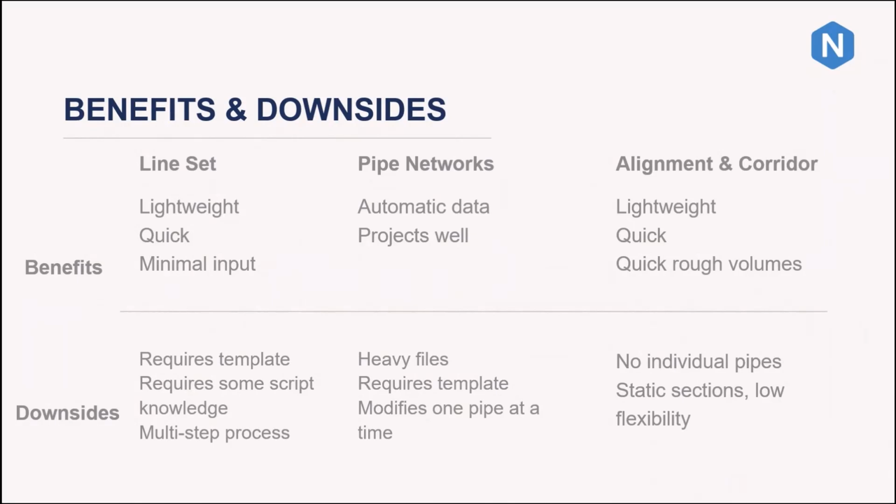If we go over to the downsides, the line set requires templates. So it requires that you have your templates already set up. It requires some script knowledge, and you need to go through the process of doing this. But once you have that set up, the line set is extremely quick to create and very, very lightweight. It's only 3D polylines that we're working with. We can create solids and surfaces from it, so very quickly you get something that you can look at in 3D.